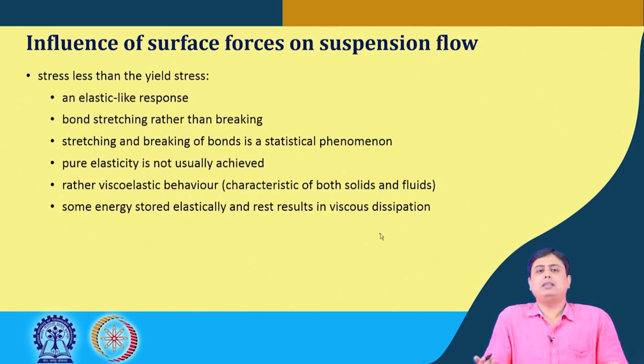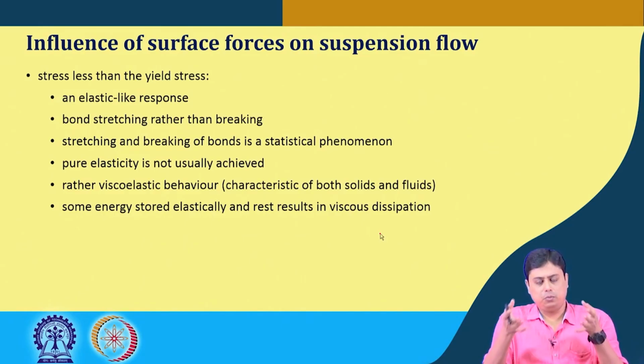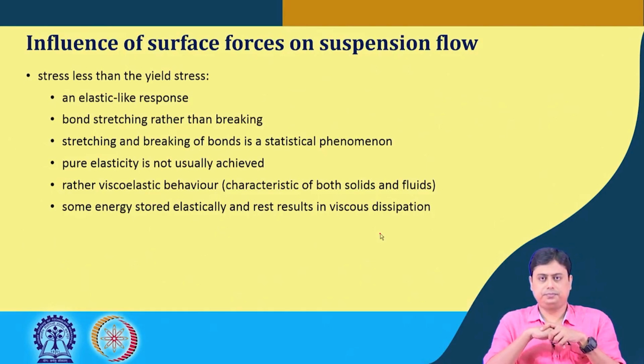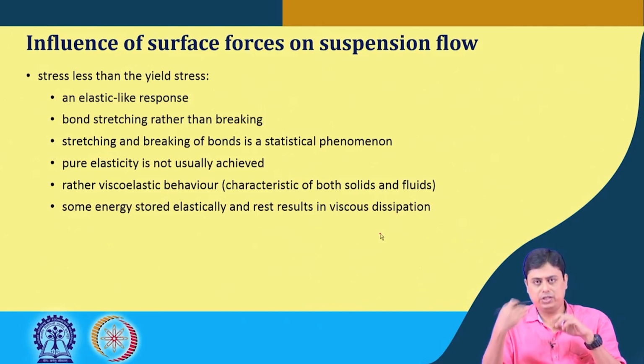Rather, it would behave as viscoelastic behavior that I mentioned earlier, with the characteristics of both solids and fluids at the same time. So, some energy applied to deform that body or the suspension would be stored elastically, and the rest would result in viscous dissipation when the stress is lesser than the yield stress, or to initiate the flow.